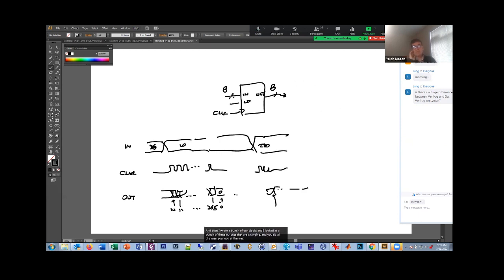You look at the waveform, and you would try to come up with a sequence of, maybe I load it with 0 first, and then I load it with 255, and then I try something in the middle, and then I run a certain number of clocks, and you look at the waveforms. Well, that takes a lot of time. You run these, and you're manually looking at these things. So that's very time consuming, and actually it's error prone as well.